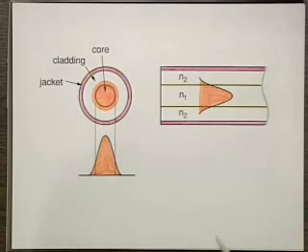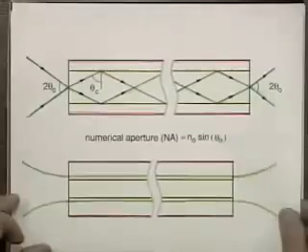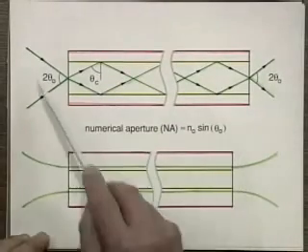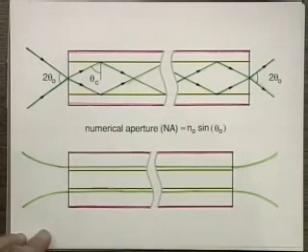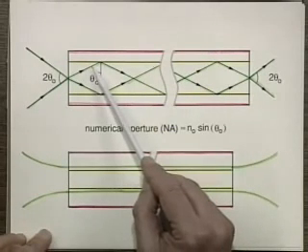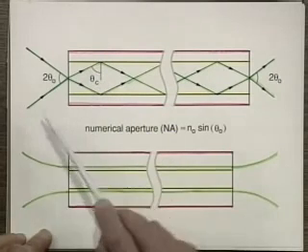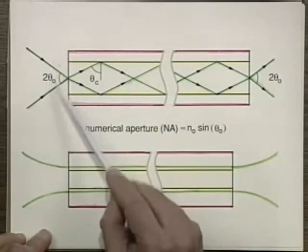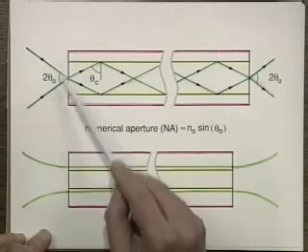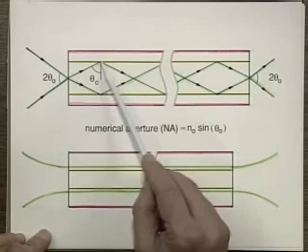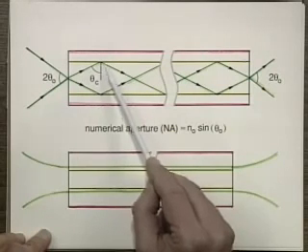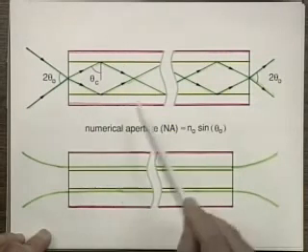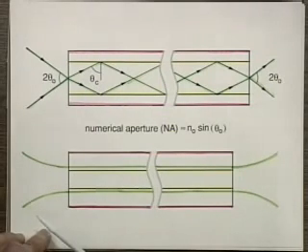Now, how does the light look when it comes out? Let's go back to the ray picture. Remember we said that the angle has to be either equal to the critical angle or bigger, and that determines the acceptance angle going in, because rays of light coming in outside this cone will not undergo total internal reflection, and will be in trouble because they won't propagate too far and they'll be attenuated.